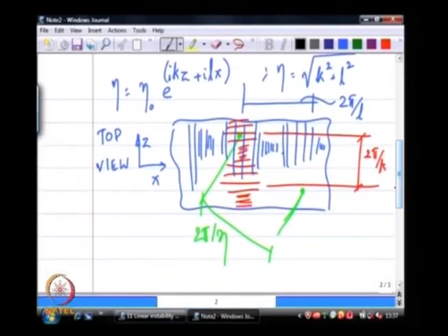So, what he showed is that if I want to look at the situation which is the most unstable, I only am interested in the situation that is the most unstable. What he says is the k equal to 0 mode gives rise to growth rates where at some value of L, the growth rate's magnitude is higher than that for any other non-zero value of k. Okay. So, it is sufficient for me to consider the k equal to 0 mode, because that is k equal to 0 or L being finite mode is where we only consider instability along the flow direction, and that is what he referred to as two dimensional modes.